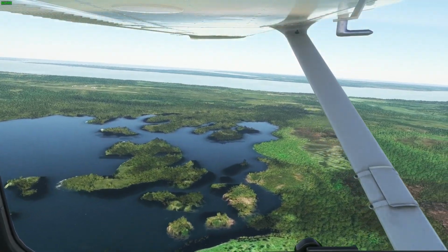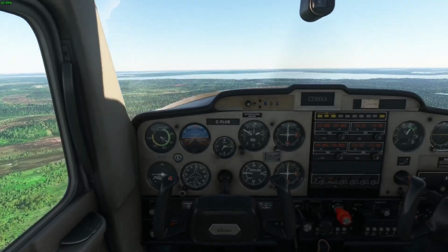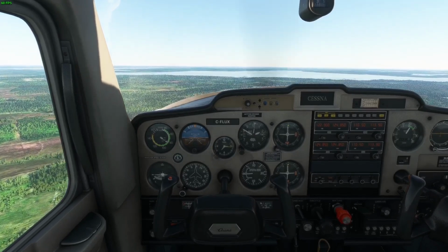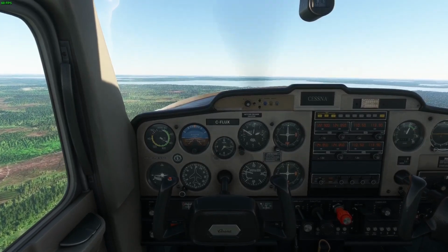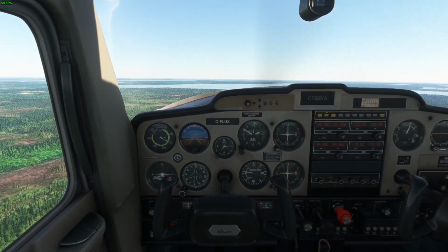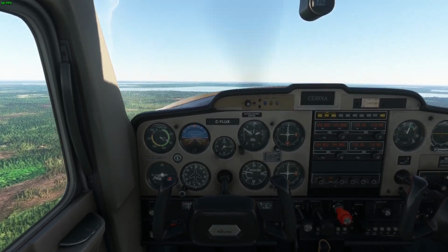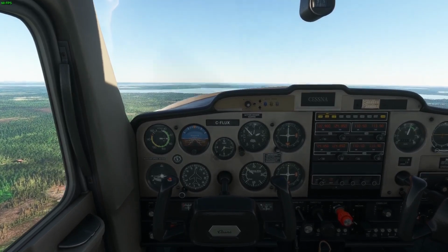Once the end of that runway gets at our 7 o'clock position, we'll initiate our left turn. We'll descend at 500 feet per minute with an RPM at around 1500 or maybe 1700 and heading at 100 degrees, which is perpendicular to the runway. So we're at circuit. Now we're pulling back and slowing the plane so I can put the flaps down.